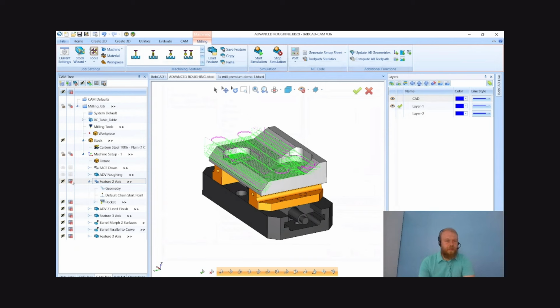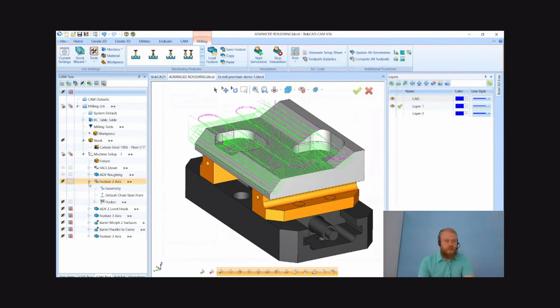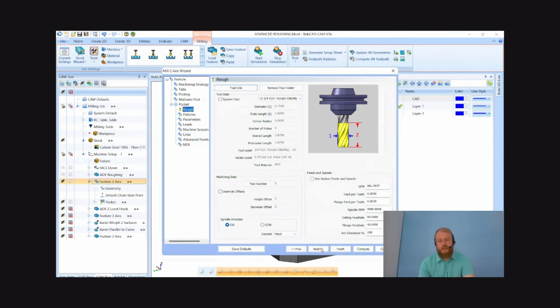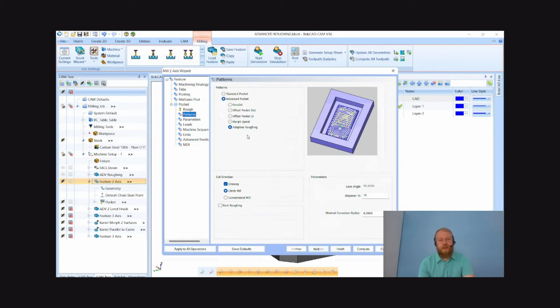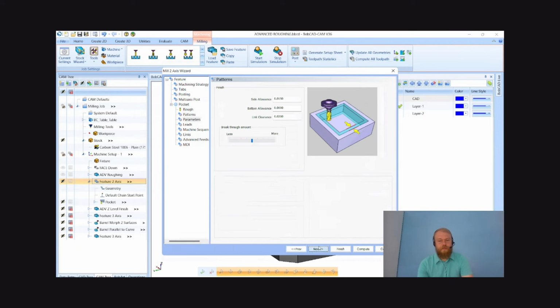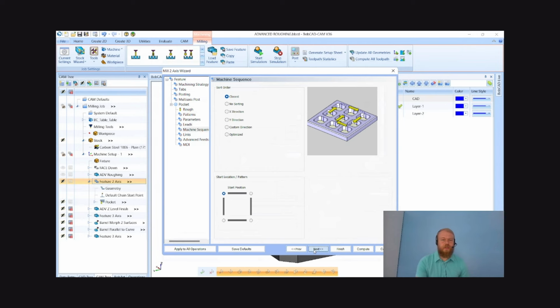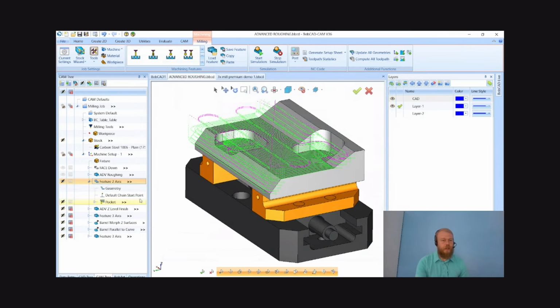All right. Let's see. So we got the pocketing down there, and it was the same as what we did for the advanced roughing, where we're selecting our tool, and then we're defining the certain cut pattern, step over, step down if we're doing multiple depths of cut, setting an allowance, leaving 15 thou for the finish pass to clean up, spiraling in, all those good stuff there. Okay, and so we'll show that all as well.